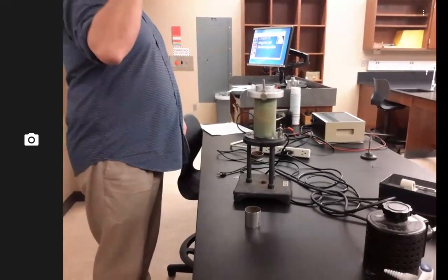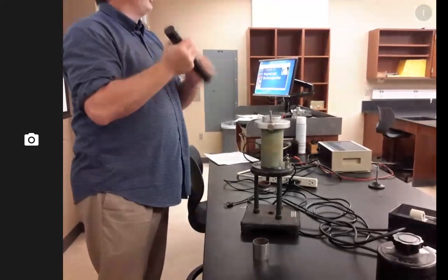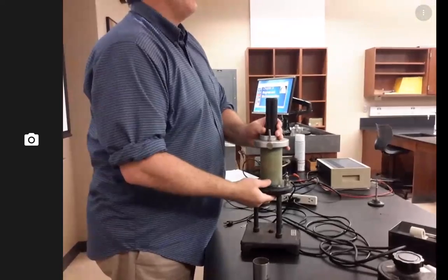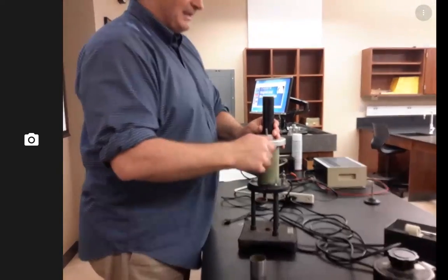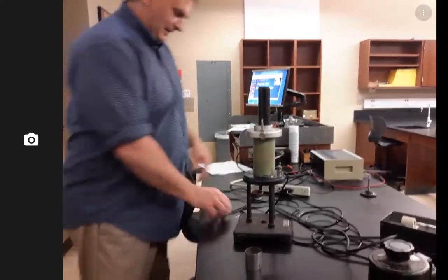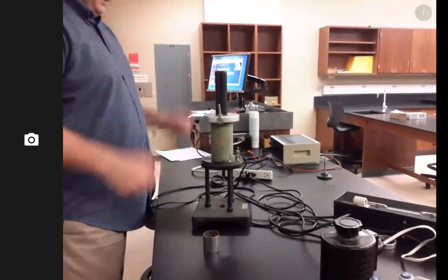This is a whole bunch of little iron rods that are insulated so I can't have electric currents flowing around in circles in them. I'm going to put this in here. What should that do to the strength of the magnetic field? Make it stronger. Makes it stronger means I can have more exciting things. So now let's try it. See, that was much, much more cool.